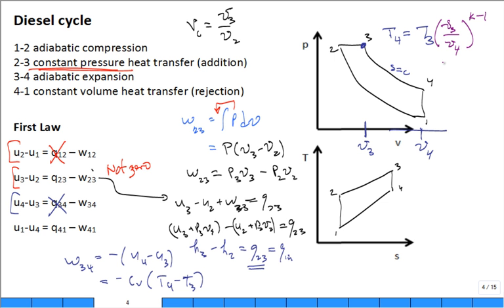All right. I still didn't leave enough room for this. Well, I'll do it right down here. Take a look at this. I want to get the V3 and I want to divide it by V4, right? If I put a V2 here multiplied by a V2, is that the same thing? So what we can do is we can replace that V3 over V4 by V3 divided by V2, R sub C. What is V2 divided by V4? V4 is the same as V1.